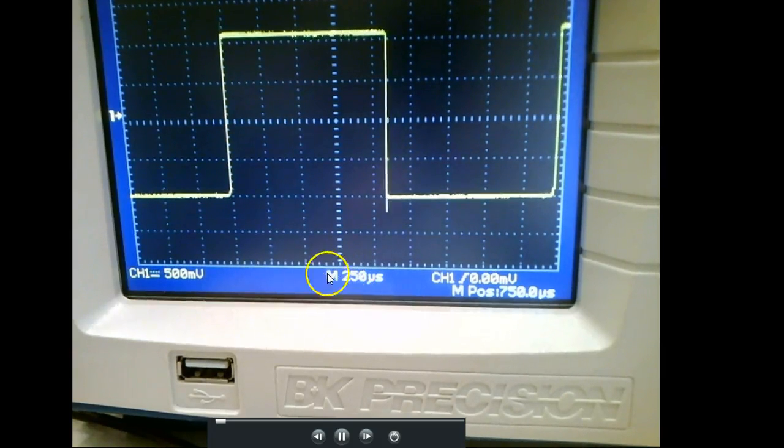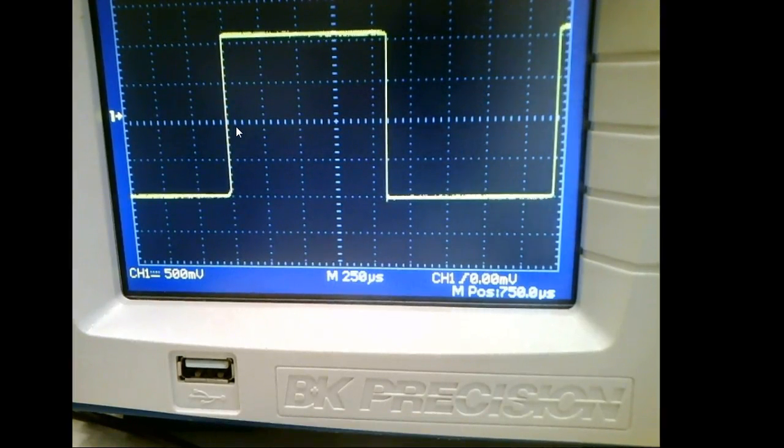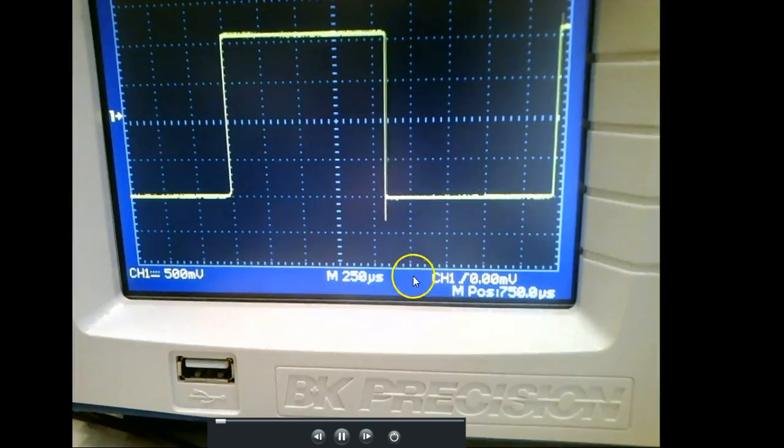And that's what I'm saying. 250 microseconds, it would be hard for me to figure out, so each one of these would be worth 0.5? Yeah. But that's what I'm saying. When you count, you don't have to worry about figuring out what this is equal to. If I got 250 microseconds per division, that means each one of these should be worth 50 microseconds. And now I've got to do all this in my head. So what we do here is count the number of divisions, right? And since we're counting in ones, each one of these should be worth 0.2.